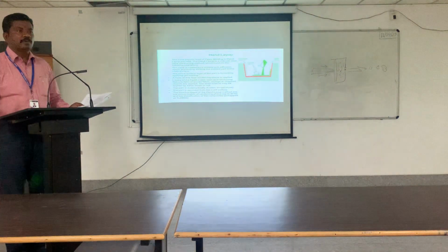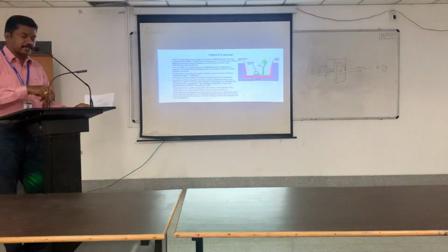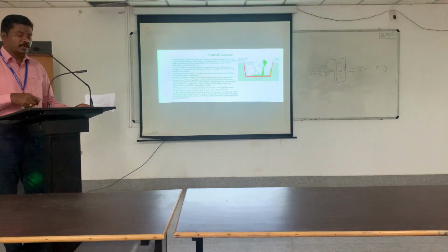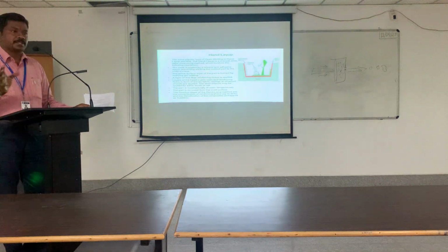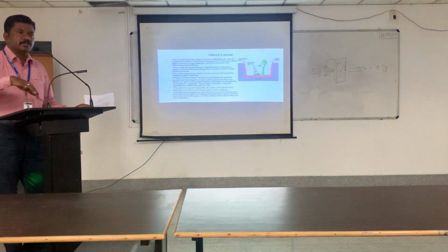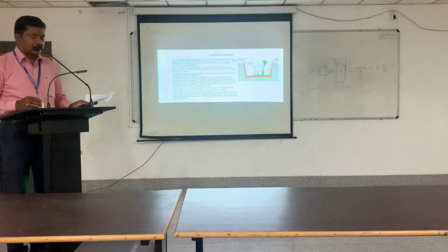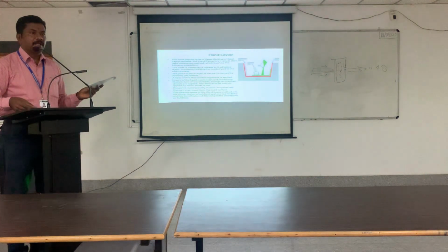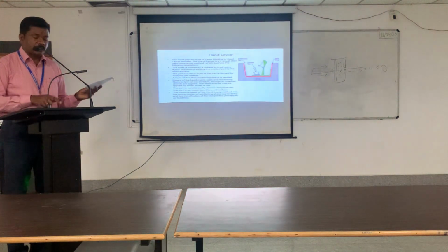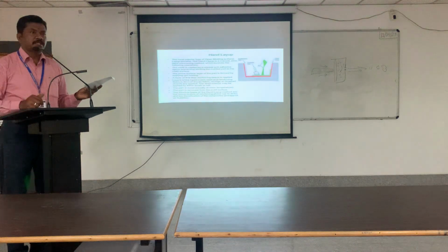Okay. These two will be taken, and first the epoxy resin should be slightly poured, and that should be spread to the entire area by using rollers or brushes. Okay. So first the resin should be spread. Okay. And once the resin is spread, one layer of reinforcement should be placed, depending on the required size.